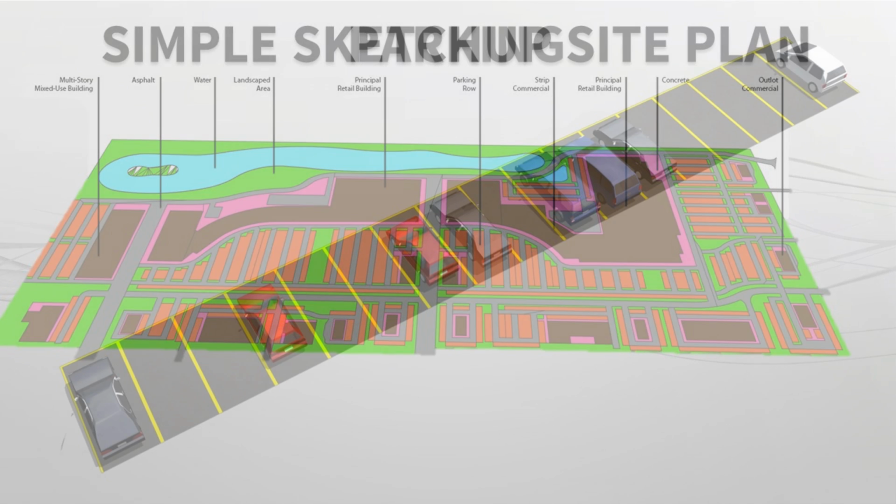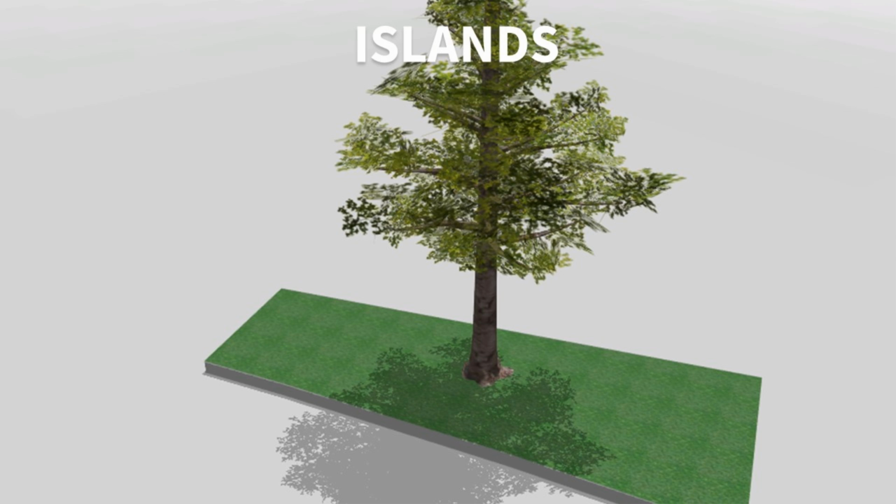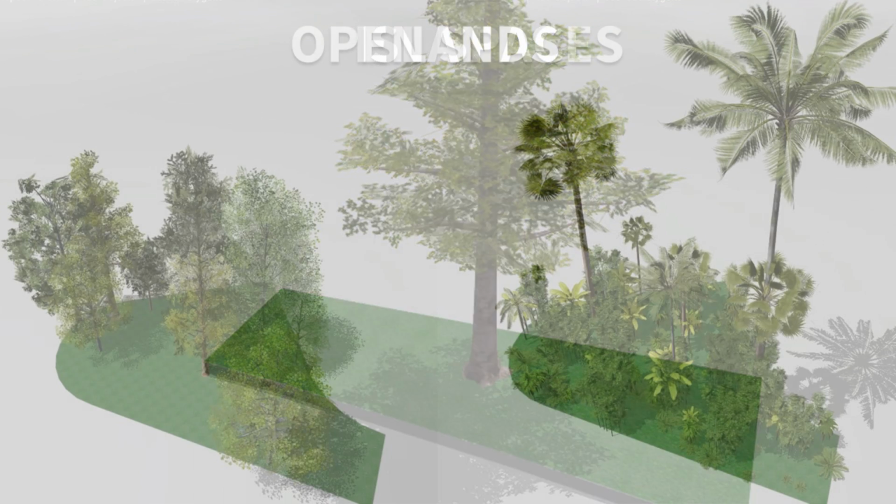And so we go to our CityEngine rules. We have a rule that just drops in parking, and a rule that just drops in parking lot islands. If we design the islands inside of SketchUp, we can apply this rule. Otherwise, that rule will put islands in every 8, 10, 15 spaces, however many we want to see.